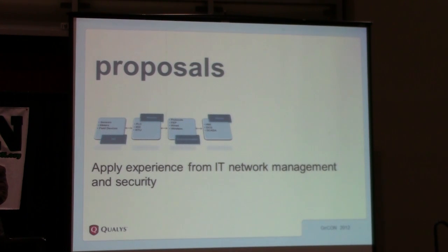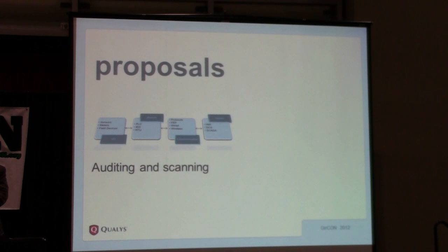And in general, as SCADA systems are now looking more and more like your regular IT systems, with regular off-the-shelf operating systems and off-the-shelf databases, just apply your experience from IT or network management and security to SCADA. Auditing and scanning will go a long way.